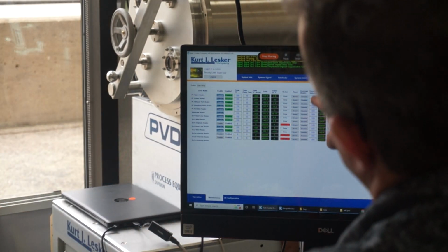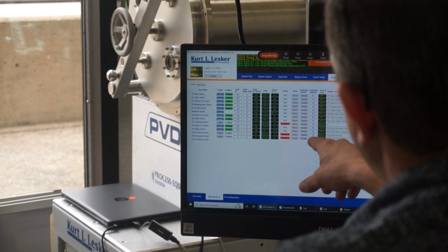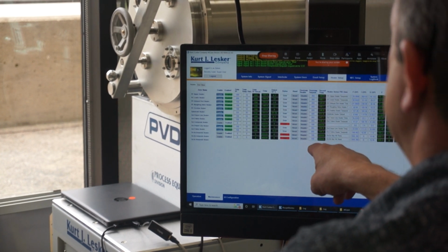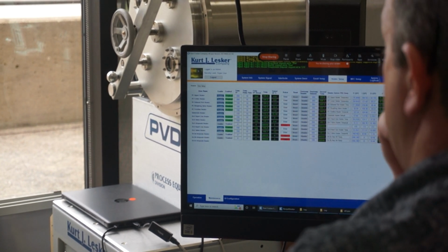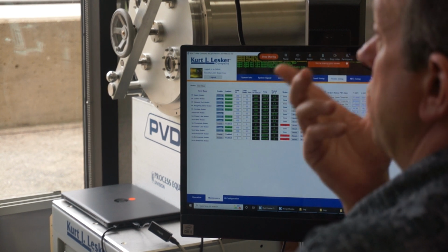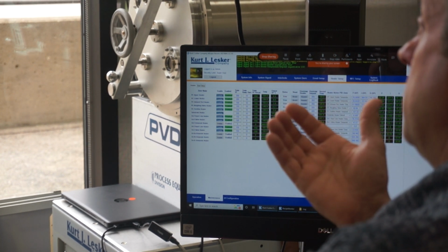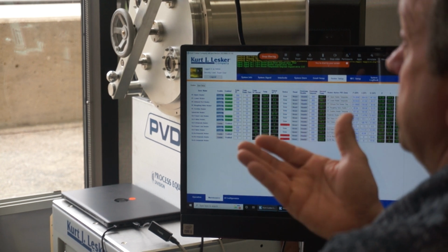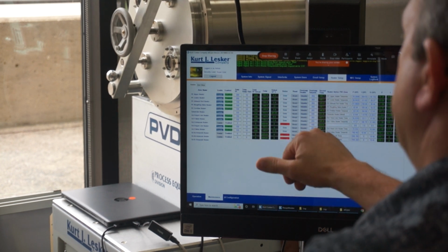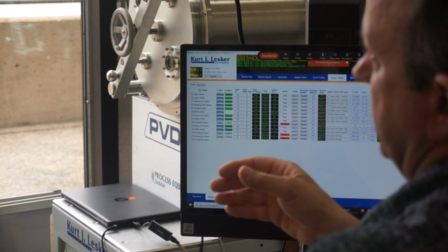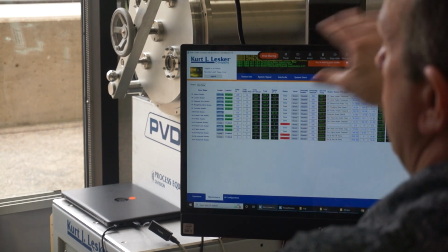So this is your over temp set point. Sometimes this matters. So in the case of zirconium, you heat it up to 75 degrees C. You don't want to overshoot because you don't want to thermally decompose it. So in that case, you might want to put the over temperature at 80, just so you don't have an overshoot.